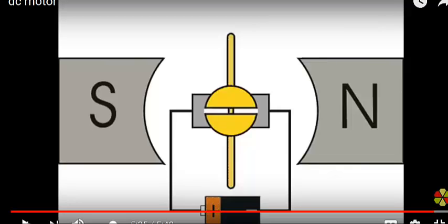So what's happening here is that the spinning armature inside the magnetic field generates a voltage opposite to the applied voltage, so the net voltage across the motor decreases as it speeds up, and there is some point where the friction or the load on the motor is balanced by the torque provided by the net voltage applied to it. It's called back EMF, and we'll talk about that again, but it's just to answer your question: why doesn't it keep getting faster and faster? That's a good observation.